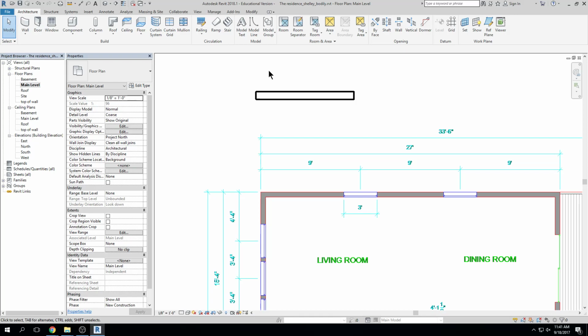For me it's just easier. If you wanted to create one wall type and then use it, great. And then when you have another wall type that you need to create, go and create that. That's fine. But usually I do similar tasks at the same time. So I do all my setup, then I create all my wall types, and then I draw all my level 1 walls. If I need to go back between level 1 and 2, I do, but I try to group things together.